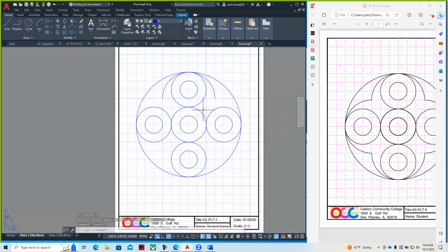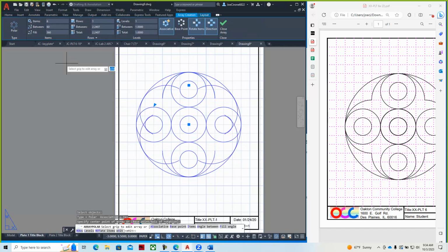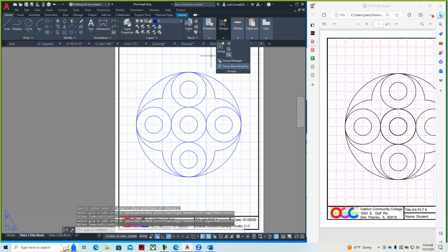And we have a video that shows the technique, but since you guys are in the video meeting, if I wanted to create an array of it, I could do that. I could just say polar array. I could select this, and I could set that for 4. Kind of like the chair. Takes a little while for the graphics to update.